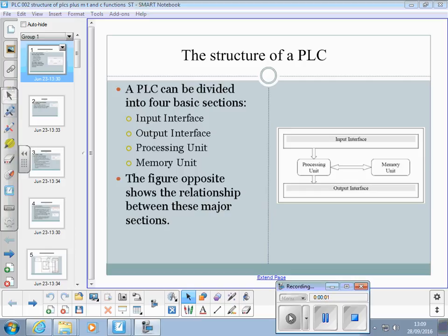Nice. This week is go through the structure of a PLC and as much as you need to know about the internal workings, a little bit about how the inputs and outputs work in terms of interfacing with the outside world. Also going to dip back into last week's notes and go through formally about the different types of logic instruction and actually how the detail of what a ladder rung must and can't contain, and also go through how the timers and counters work.